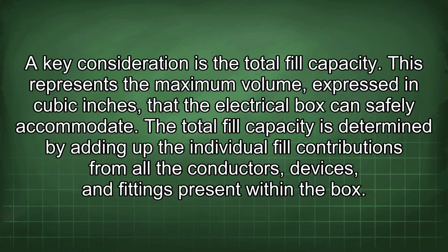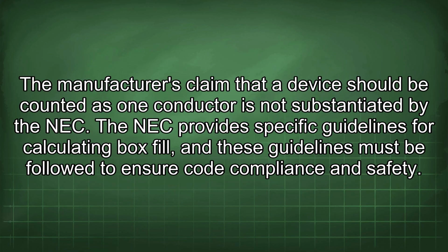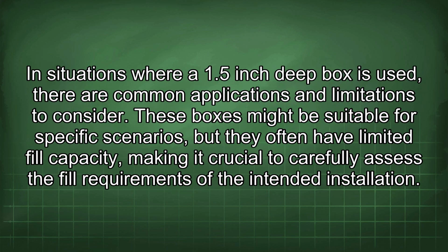present within the box. The manufacturers' claim that a device should be counted as one conductor is not substantiated by the NEC. The NEC provides specific guidelines for calculating box fill, and these guidelines must be followed to ensure code compliance and safety. In situations where a 1.5-inch deep box is used, there are common applications and limitations to consider. These boxes might be suitable for specific scenarios, but they often have limited fill capacity, making it crucial to carefully assess the fill requirements of the intended installation.